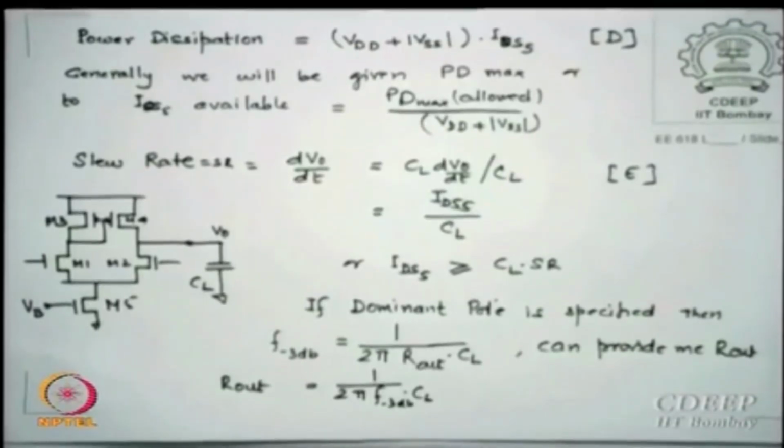I say okay, how much heat sink am I providing for the chip, that is called the thermal resistance available to the ambient from the source of heat. So I solve a thermal conductivity equation, continuity equation, and figure out for given thermal time constants, the conductivity of the materials I am going to have in series, and how much heat I can dissipate so that temperature does not exceed this. Delta T by delta P is called thermal resistance.